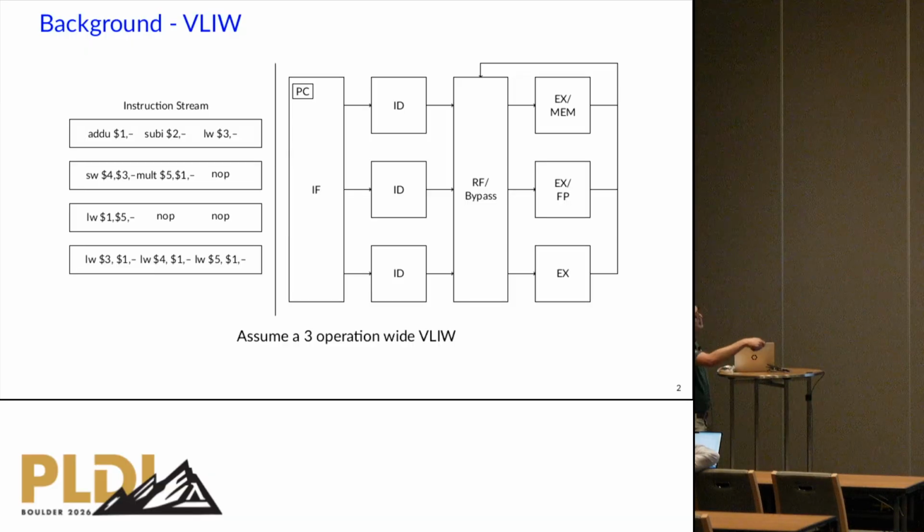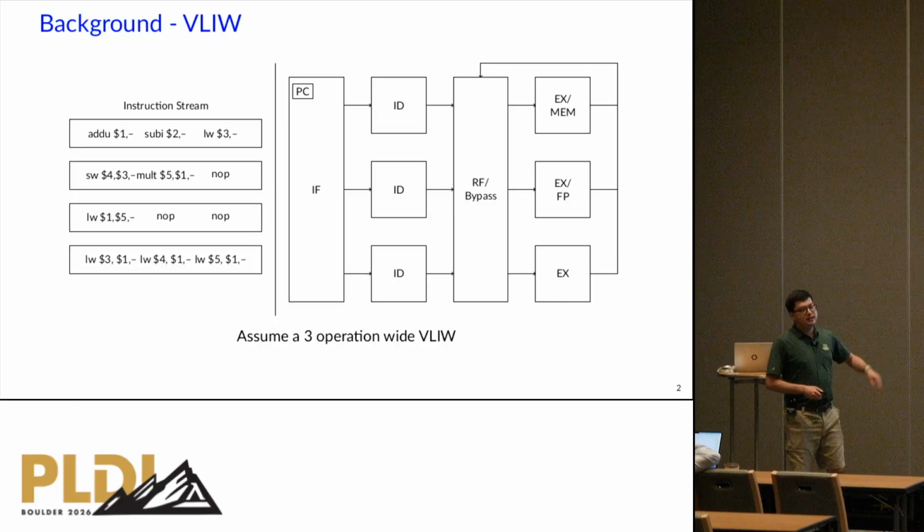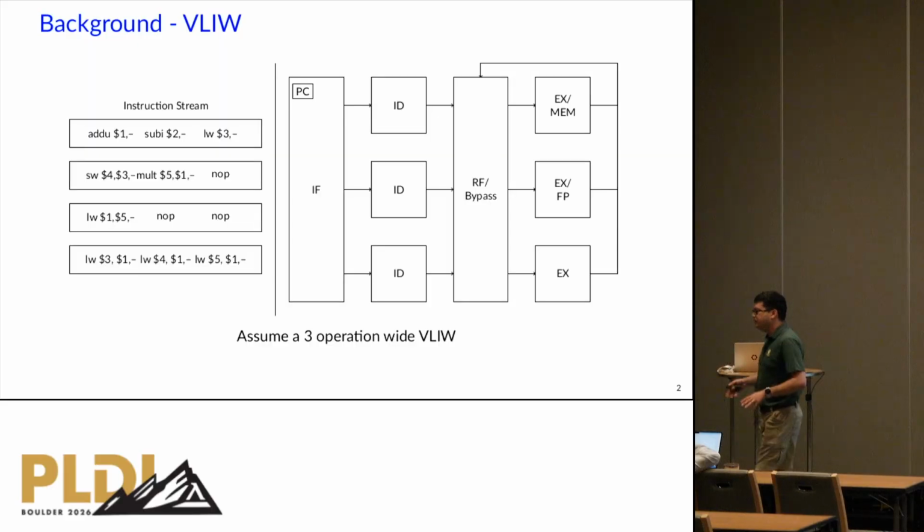So the idea basically is that a VLIW processor is much simpler than what we consider our modern superscalar processors, and these operations are going to have to be scheduled by our compiler. To maintain alignment, we oftentimes pad these instructions out with no-ops, although we try to then compress them afterwards with specialized hardware. But that's the basic idea and a very simple version of a VLIW.